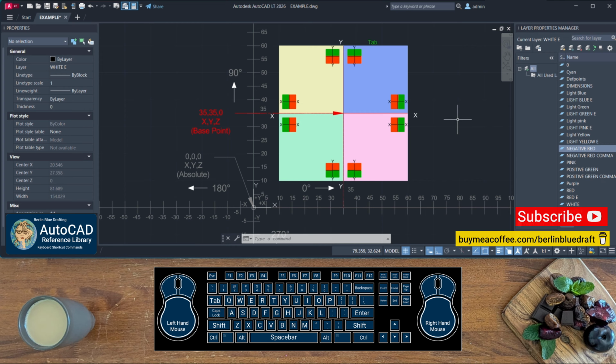I will be using blue, yellow, green and pink quadrants. This will be from the first corner point or base point. Note that the positive and negative will operate differently than typical quadrants when applying the rectangle command. The blue is from 0 to 90 degrees, upper right. The yellow is from 90 to 180 degrees, upper left. The green is from 180 to 270 degrees, lower left. And the pink is from 270 to 360 degrees, lower right.